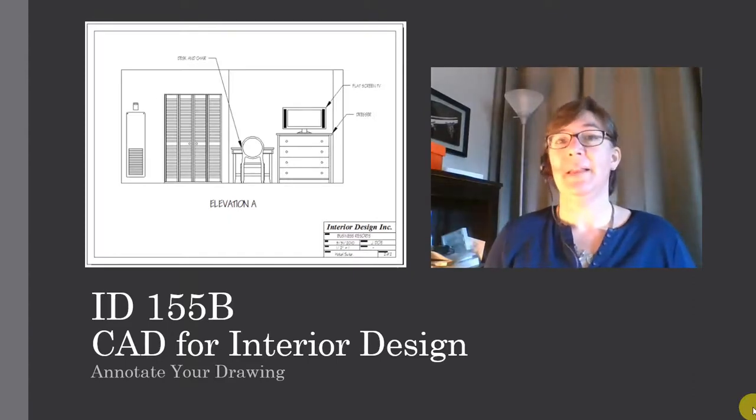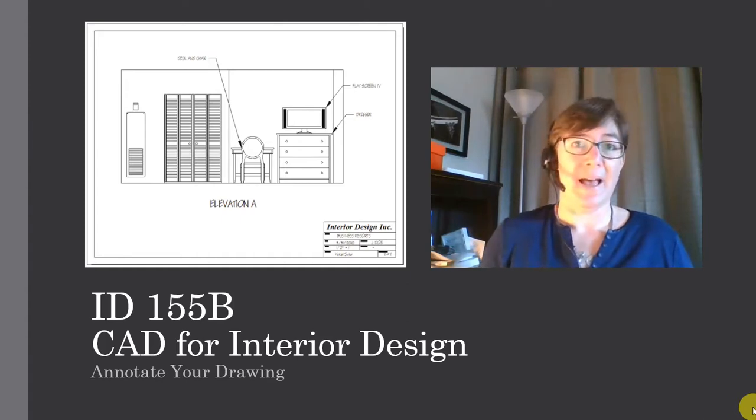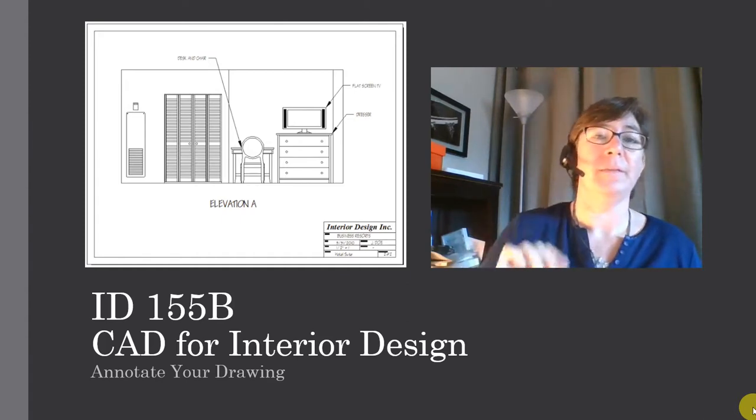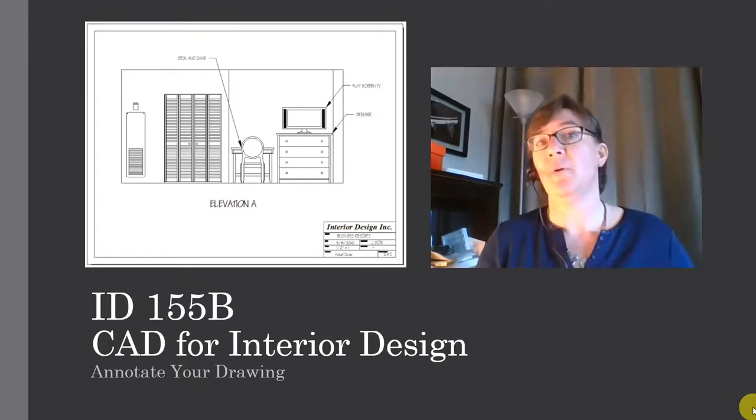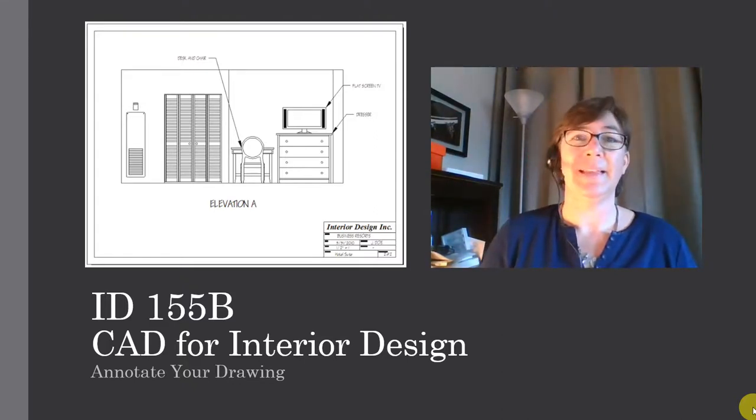Okay, everyone, multi-leaders are another powerful tool for annotation, and I recommend that you always use the multi-leader command and not any of those older or legacy leader commands that are still available in AutoCAD.